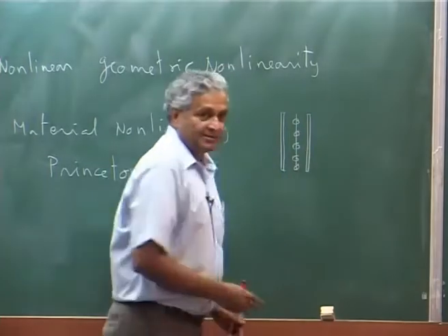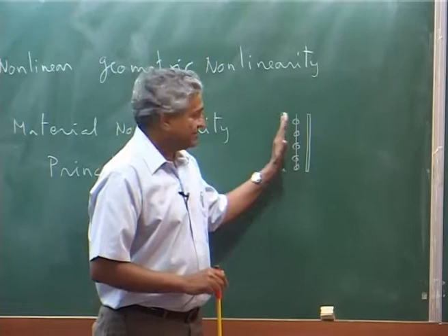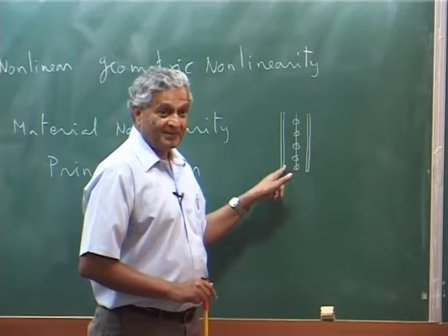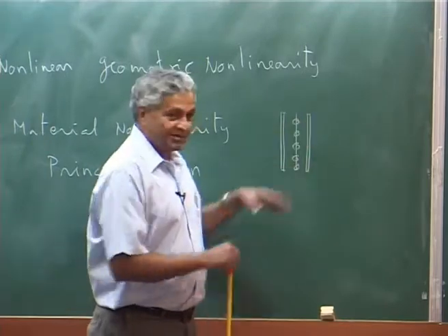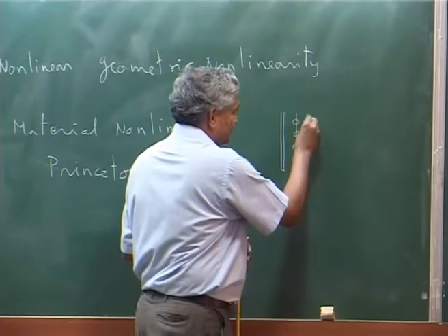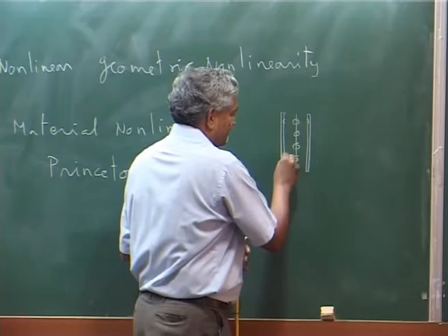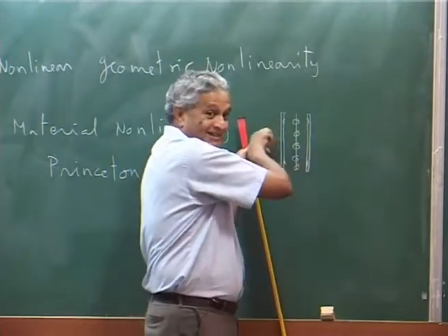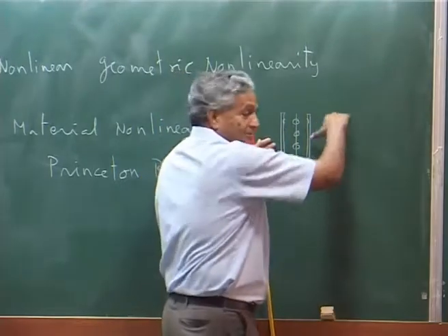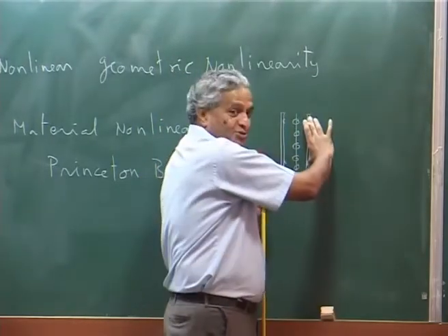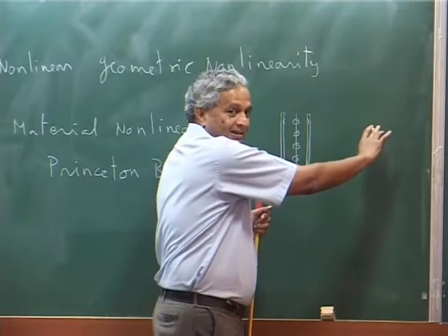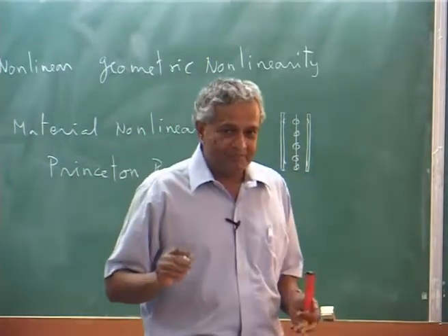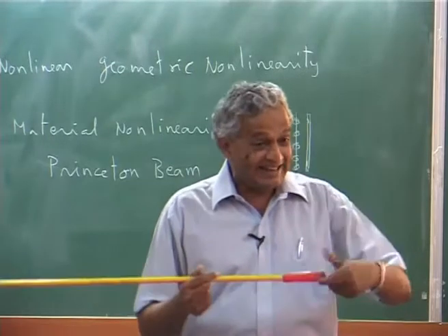I have shown this is one plate, this is another plate, in between there is a plate with a lot of ball bearings and there is a groove in this, it will come and sit in the groove, okay. You close it and the blade will be tightened from this side, you can rotate freely. This is attached to one, this is attached to the blade. So, you can easily change the pitch angle of the blade without any difficulty.